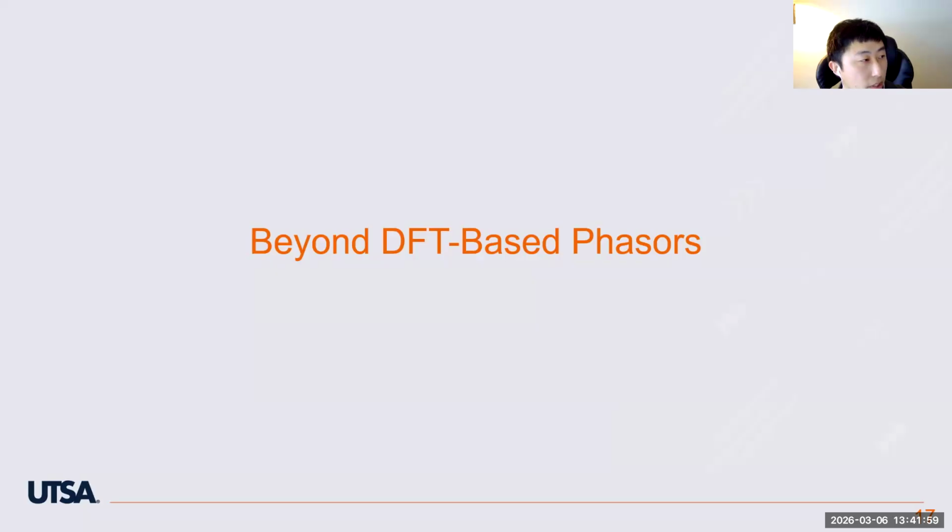We would like to verify that by hardware PMUs. But what we learned is very clear. The DFT-based PMU phasors cannot accurately capture high-frequency oscillations. So with that, the next question is what to do if we know DFT is not good for high frequency. So next, I'm going to show some initial efforts we did to move on this topic.